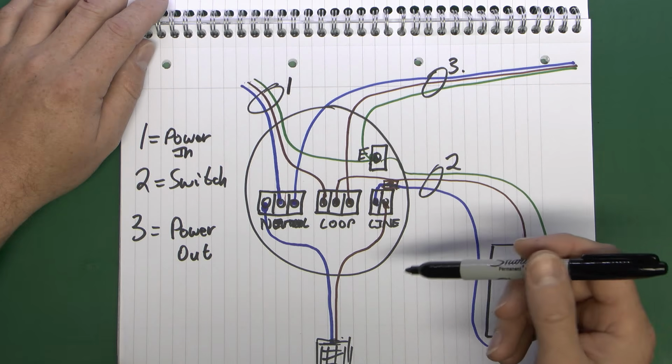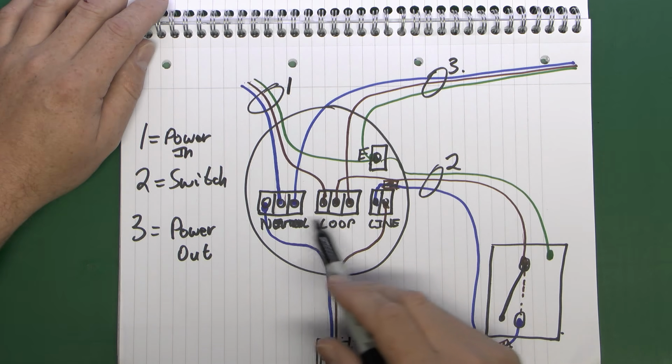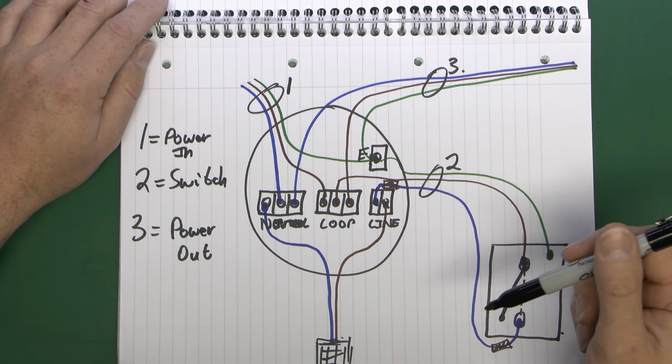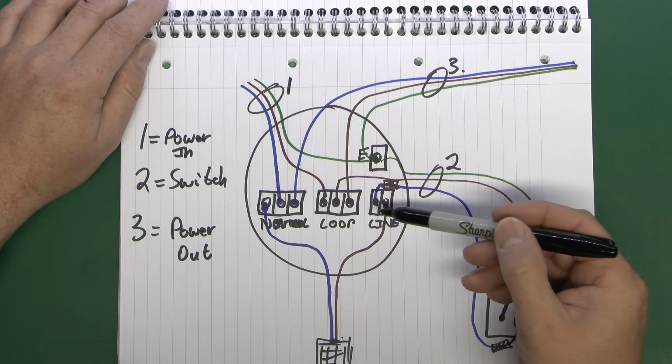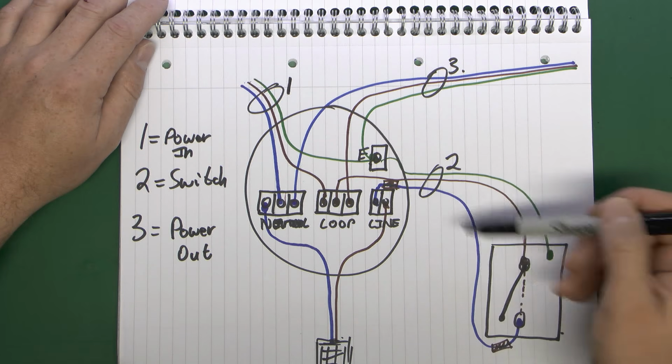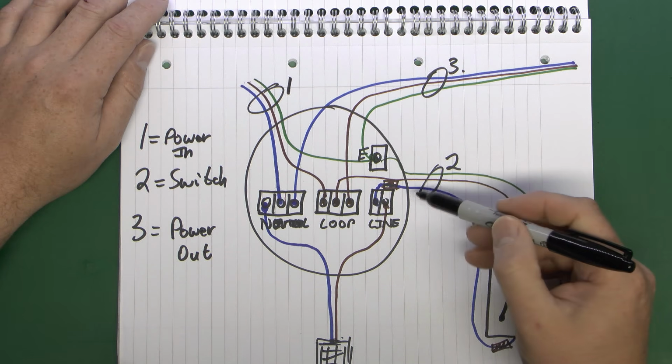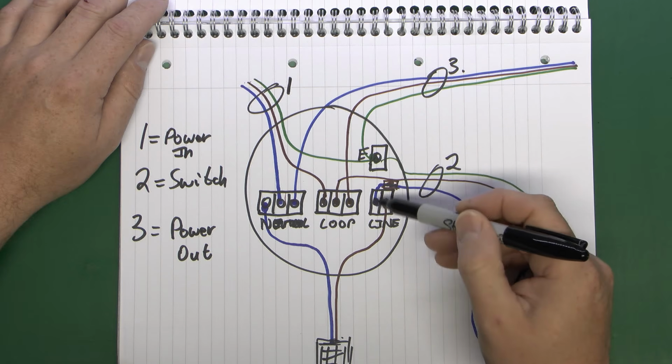And if you're going to buy a new light fitting that does not have these terminals inside, before you rip all this down and make a right mess, it's absolutely essential to identify which one of these is the one going to the line terminal here, as in the one that comes from the switch and has not a neutral in, but a line and a switched line.